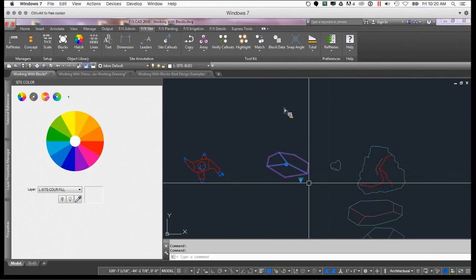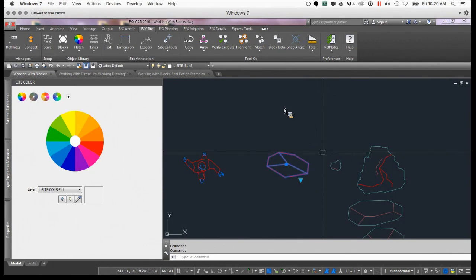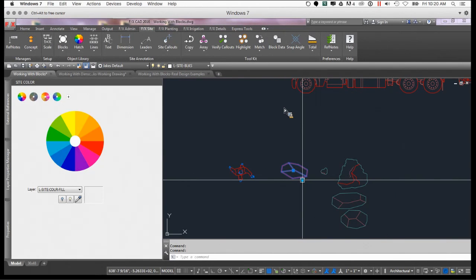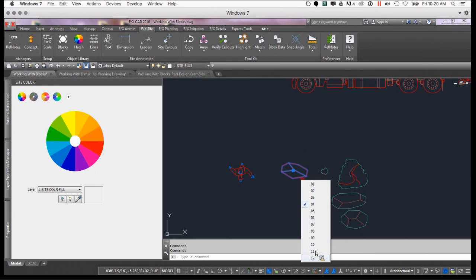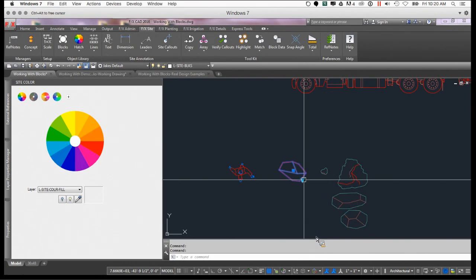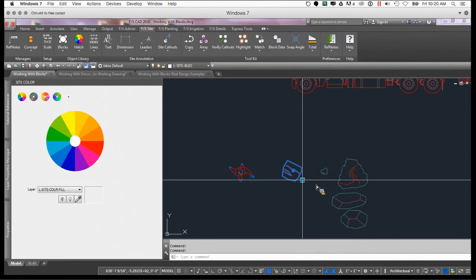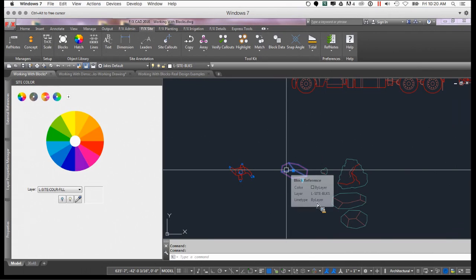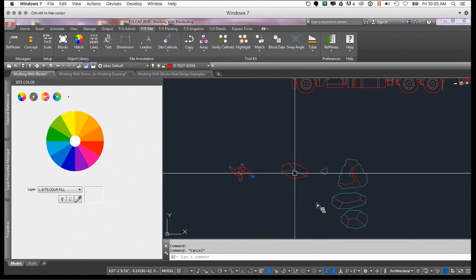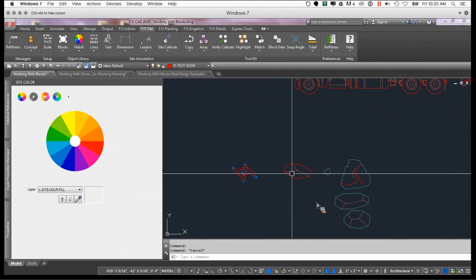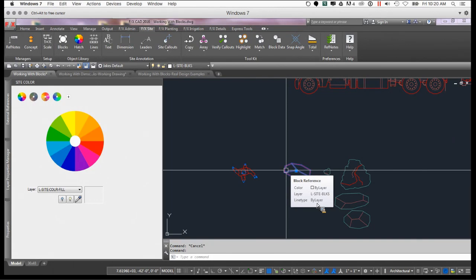There are different ways that you can create dynamic blocks. We're actually going to go through how to save a specific type just in a real quick instance. But this guy has a list of different shaped boulders. And what's really neat about this is it's basically a visibility state, where it's just toggling different versions of a boulder so that we can function with the same block throughout the drawing but still not have that static copy-paste look, and still be able to only have one instance of that block definition, not several types of block definitions.